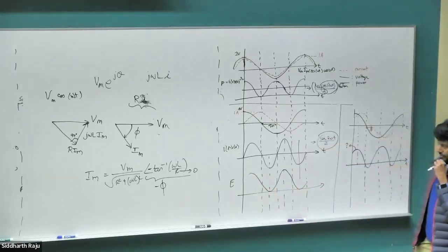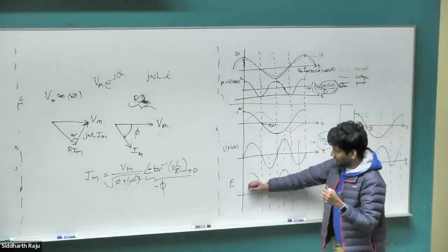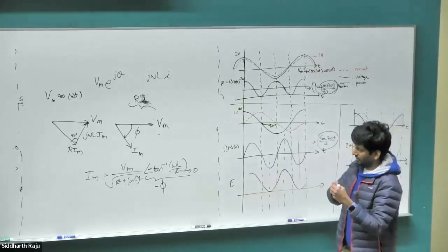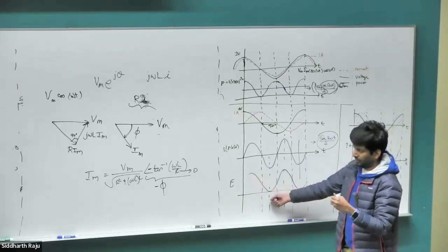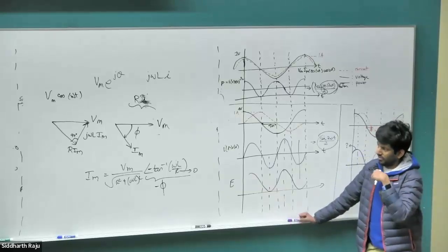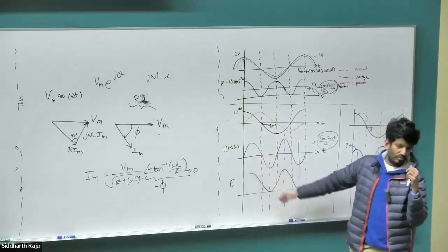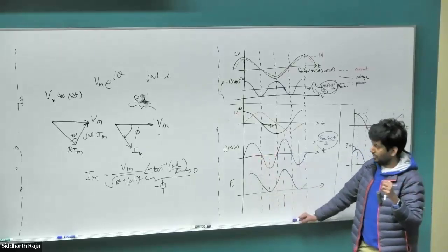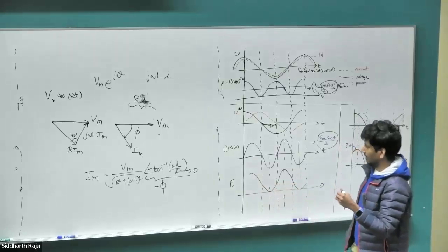Right? So basically the energy going into the inductor is always going to be some positive value, going in, coming out, going in, coming out. You can't have negative energy because an inductor can't generate energy in any sense. So when people say energy goes back and forth, that is not what happens. The power flows back and forth between the source and the load. The energy is going into the inductor and being taken out of the inductor, but there is no negative energy coming from the inductor.